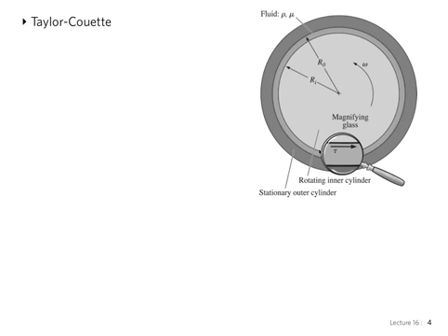It actually is moving axially. But there are other situations where you have a rotating shaft which is lubricated in this way. So you want to calculate things like the torque required and so on. So the flow in this narrow gap between two concentric cylinders is approximated very well by the Couette solution.